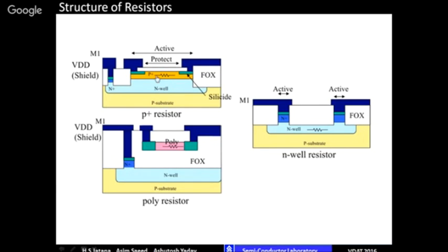This resistor is sitting here, so it is protected from interference of the substrate now. You have shielded it just like a coaxial cable concept. So this is a shielded resistor. But again it will have some VCR because of depletion.